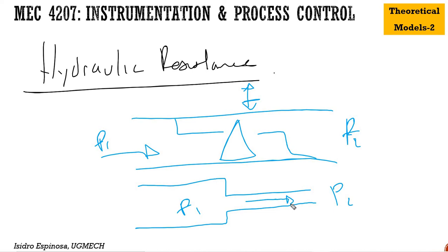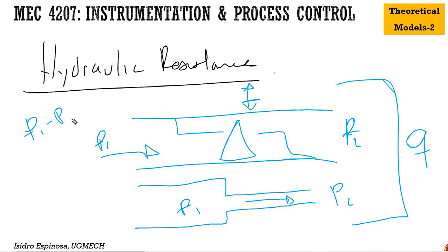So what do we want to say, or what is the meaning of hydraulic resistance? As we see in the graphics here, hydraulic resistance is the resistance to flow which occurs as a result of a liquid flowing through the valves that we are observing, or, in relation to the pipe, the changes in pipe diameter, for example. So the relationship between the volume flow rate of a liquid, which we can call Q, through the resistance element, that is the valve, and the resulting pressure difference is the variable that we are measuring in order to understand its value, right? In this case, the pressure difference is simply pressure 1 minus pressure 2. Okay, so now pressure 1 minus pressure 2 is equal to flow rate.